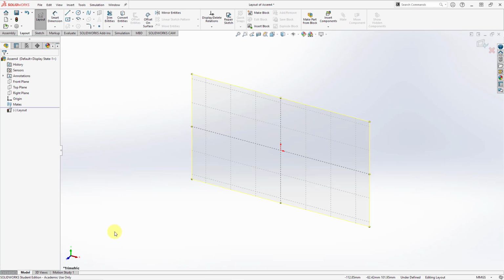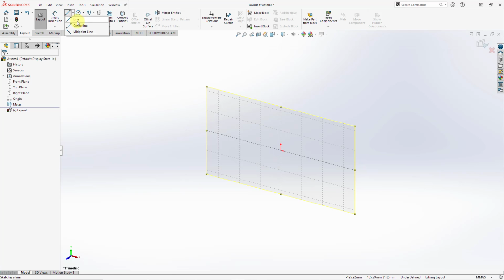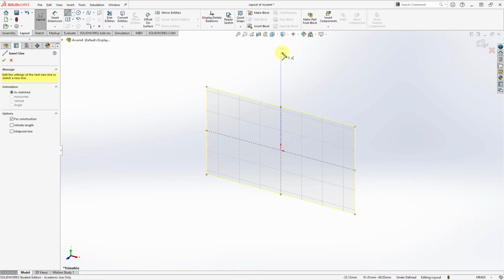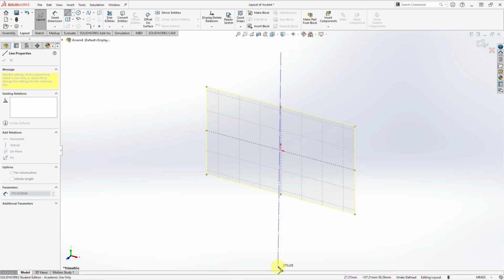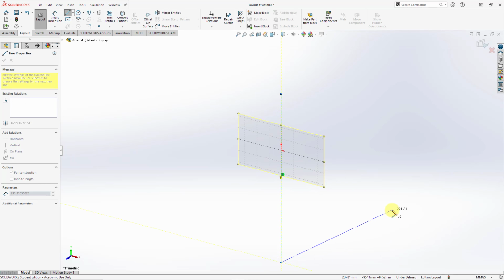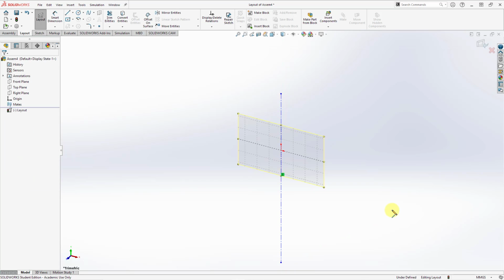And by clicking on that, it automatically puts me into creating a 3D sketch, and the 3D sketch is initially with a 2D sketch located on the XY plane. So let's do that. And for the first entity, well, let me put in a vertical center line. This will help me with some stuff later on, and let it inference into that location and drag it down about so much. Let's hit the escape key.